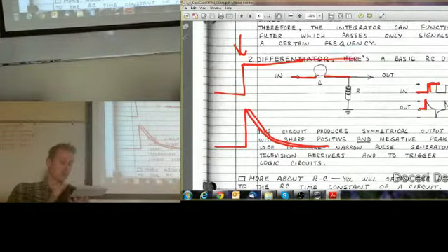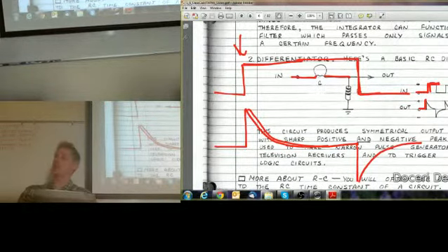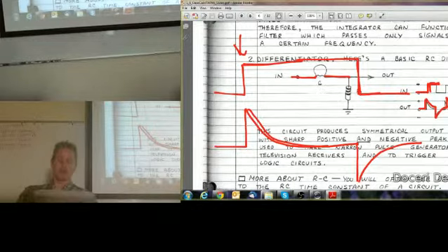Now if we bring that signal low, this fast moving part is going to tend to get through the capacitor. But then when you get to the DC part of the signal, again it's not going to let that signal pass through. So that's why you wind up with this little spiky type signal. I don't really know what you call that signal. But that's the type of signal you would get on an oscilloscope if you had a differentiator.